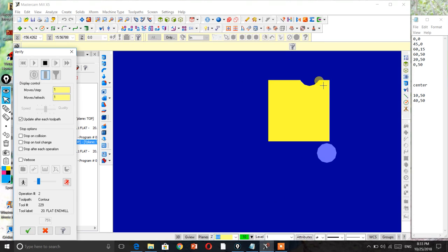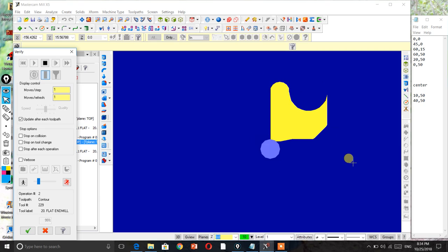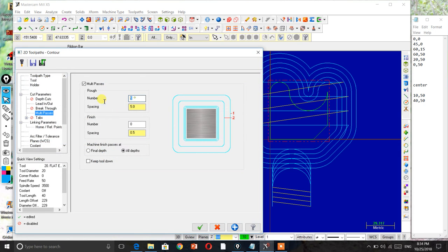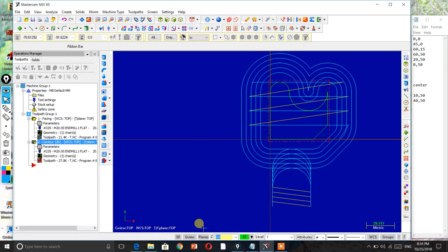So if you decrease the multipass value by 2 units, you will get the exact position, and you can save one more rotation of the tool. Although if you don't want to do that, it's okay. You can see this particular operation is perfect, and if you want to decrease one multipass, you can also decrease it by 4, and let's say okay, and then regenerate it. So again, this is okay, this is perfect.